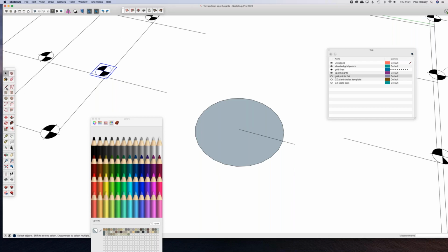Now, I could repeat that process for each of the lines, or if I select the line, it's been split because it crosses the circle. So I use the Shift key to get both parts. If I use the rotate tool, which is on my large tool set on the left, place the rotation point in the middle, and then, whoops, start that again. Draw across, pick my line, and then pick my rotation. I want to make a copy.